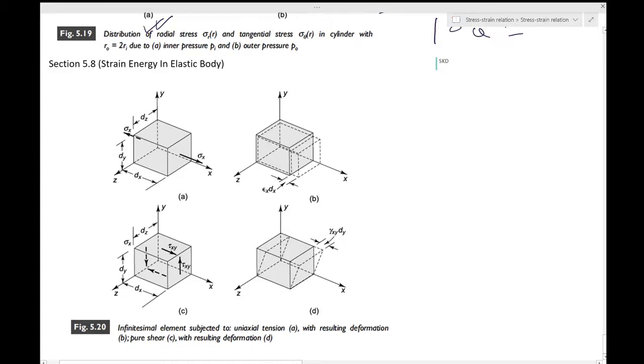In terms of the deflection delta, in terms of force F, and in terms of the deflection delta and the force F. We shall find the latter form, U is equal to half into F delta, most convenient for our present analysis. The first equality in equation 2.10 is about delta only, the last one is about F only, and the middle one is about F delta. So we'll use the middle one which has both force and deflection in it.